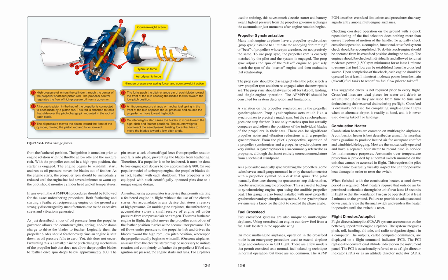The engine begins to windmill, start, and run as oil pressure moves the blades out of feather. As the engine starts, the propeller RPM should be immediately reduced until the engine has had several minutes to warm up. The pilot should monitor cylinder head and oil temperatures.